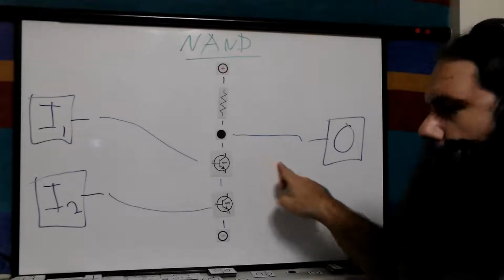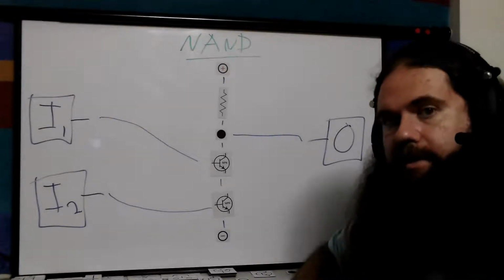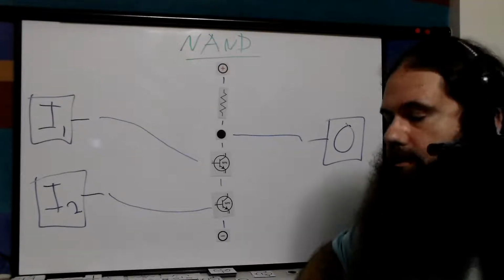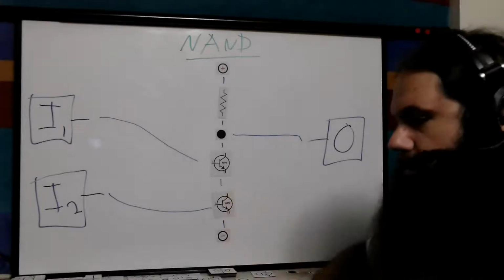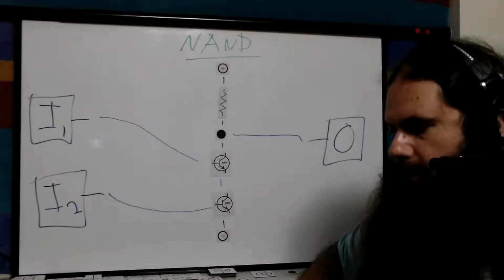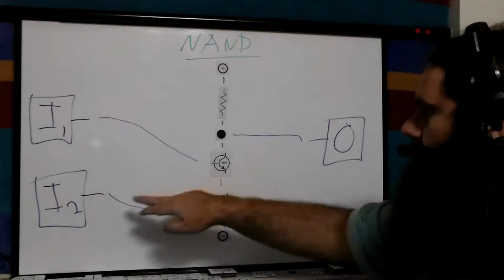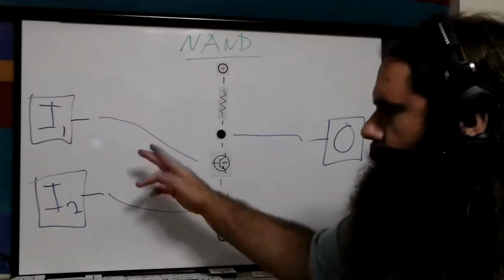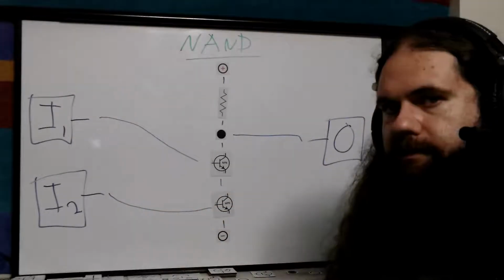We're getting about 0.4 for these imaginary transistors. So we're measuring about 0.4 at the output, and that is going to be too low to turn even a transistor on. Transistors generally, like this, are going to want 0.7 or so. And for anything, it's low enough, so high and high, we're getting a low. Let's turn one of them off. In fact, let's turn both of them off just to start.